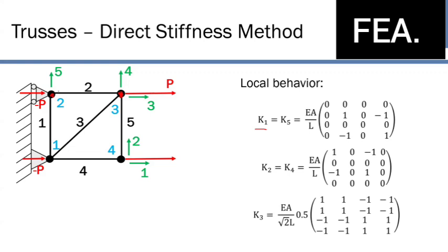So with that, when we're looking at this node, in the one direction, it's obviously a horizontal member. So in the one direction, left and right, a displacement in that direction leads to a force in that direction. So we get a one-to-one influence there. In the two direction, whatever displacement we apply in the perpendicular direction, that's not going to cause any stiffness in that horizontal direction. So if I move it this way, if I move it that way, that's not going to really influence me in this direction. It's not going to cause any stiffness for me there.